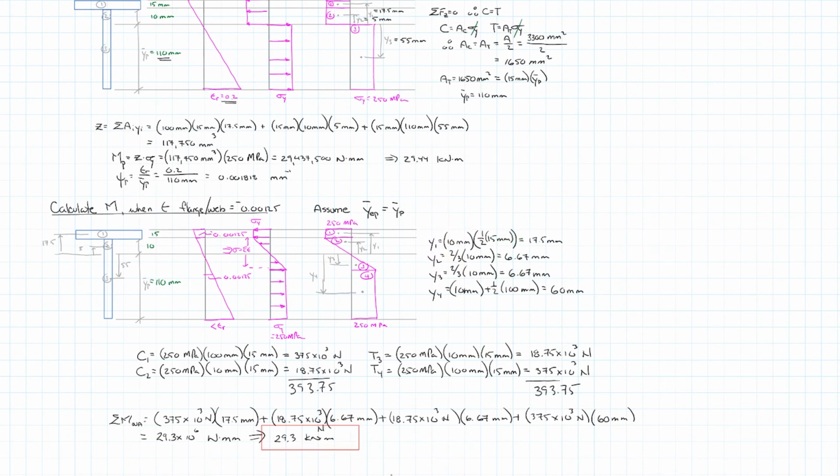And it's worth noting that that is almost the same as the plastic moment, because we haven't actually shifted that much of the material of the cross section back into the elastic range. The vast majority of this cross section is at its plastic capacity, and so we've only reduced the moment ever so slightly, with only 10 millimeters either side of the neutral axis carrying load elastically.